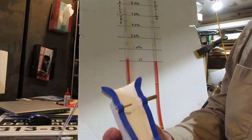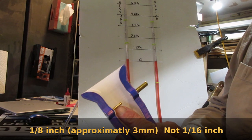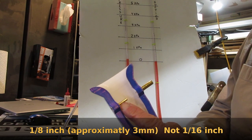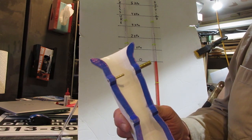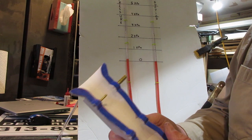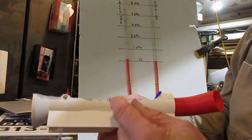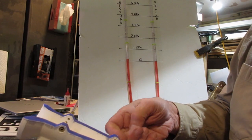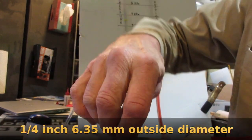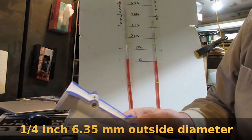So for the probes, this is 1/16 brass tubing from the hobby shop. I don't know what metric equivalents are available, but in any case, when you're putting it in, if it's a little too tight, you can just run a drill through the hole, and I would check the fit of the fatter tube as well before committing to sticking the skinny tube in.